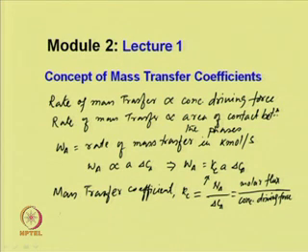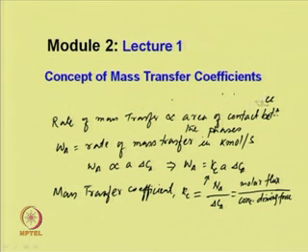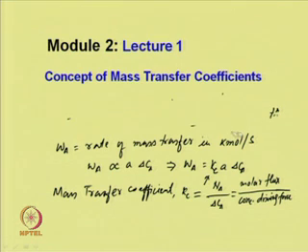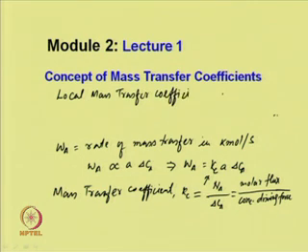In this case, there are other mass transfer coefficients. One is called local mass transfer coefficient. The local mass transfer coefficient we can define by the local flux divided by the local driving force. Local mass transfer coefficient we can write as local flux divided by local driving force.